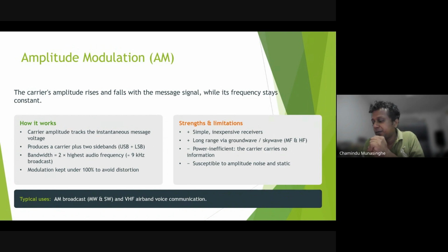So I don't know whether you guys, I know when I was a kid, AM radio was here, AM and what you call medium wave and short wave, amplitude modulated broadcast radio stations were there, and we used to build these very simple radios, like what you do is tie a wire to the wire fence, add a diode and a cap, and you can listen to the radio with a small crystal earphone.